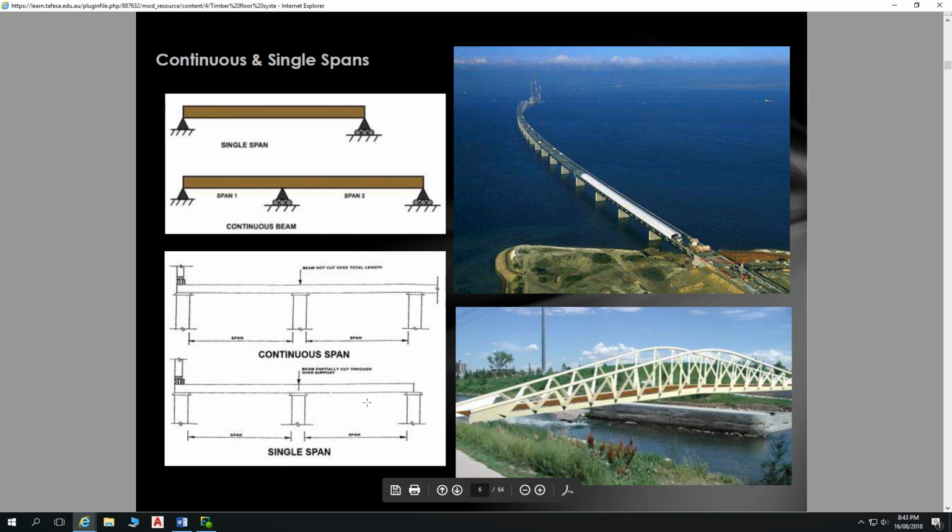But just recently, a couple of weeks ago, I was pulling a floor out of an old building because I wanted to salvage all the jarrah from it. But I stopped at one floor because when they built it, they cheaped out and they bought timber which is quite wavy for doing their bearers. And to counteract that, they did cuts above all their stumps. So you can have a piece of timber which is slightly bent. You put that in as a bearer with the curve facing up. You do a cut in the middle, straight over your stump, which enables your bearer to settle.